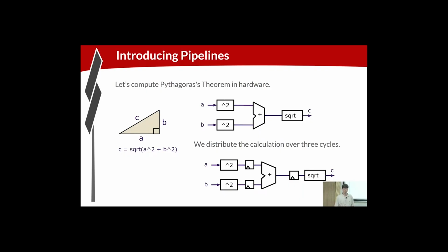Okay, so we have to partition the computation so that we're doing some logic in one clock, more logic the next clock, more logic the next clock. So simplistically, I've just divided these 3 steps into 3 pipeline stages by putting flip-flops between each computation. Square root itself is a very complex computation, and realistically, we would not be able to do that in a single cycle, but this is just an example. Let's pretend. So we've got our three-stage pipeline to do these computation steps.